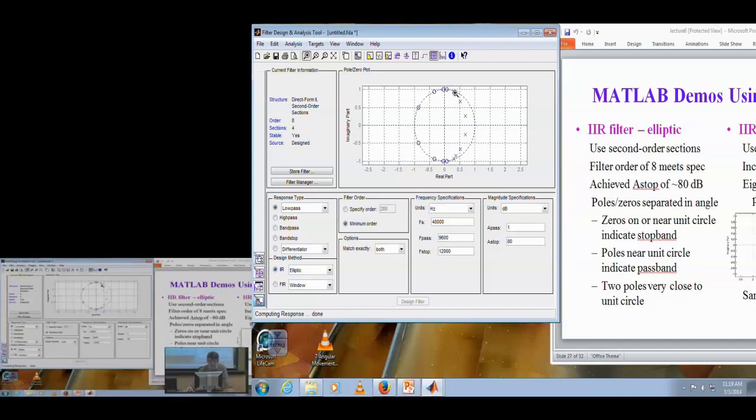So it's 2 pi times the passband frequency divided by the sampling rate. And so how do we convert a continuous time frequency to discrete time? Multiply by 2 pi and divide by the sampling rate. And this is lecture 1, right back in sinusoidal generation. You'll be with us the rest of the semester. Fundamental. So that angle should roughly be 2 pi times 9600 divided by 48000, roughly.